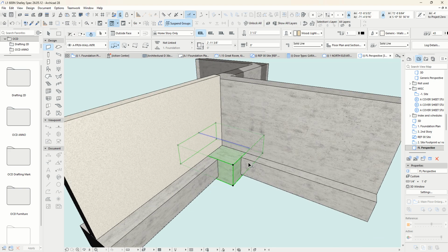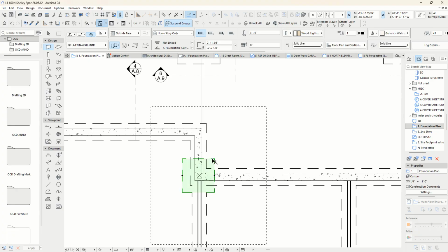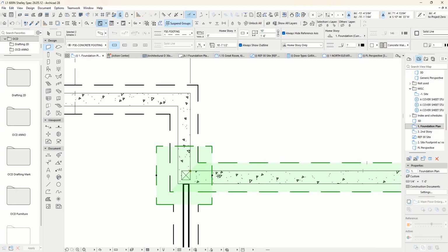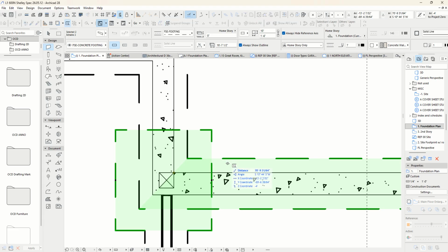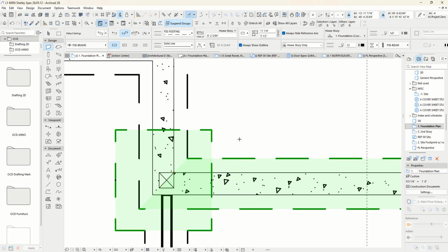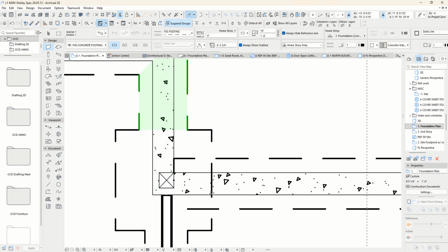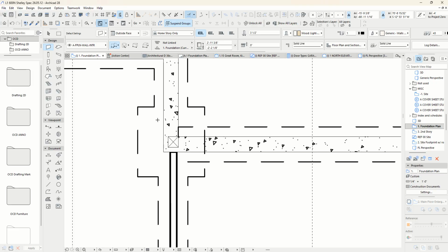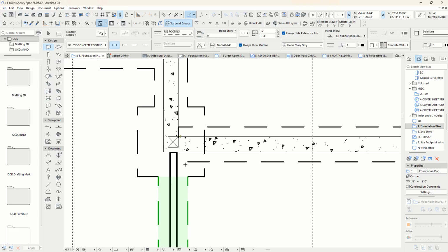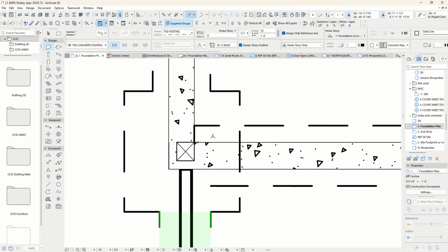Back to the footings. So these are beam tools. You can see the reference line there and the reference line there. And if I look at them in plan, I notice that my reference line for this one's down here. My reference line for this one's here. And so if I want those to merge, I have to move this reference to here. Now in the perpendicular direction, with this one merging onto this, all I have to do is extend this footing to the origin point there and see how it smooths right up. And that's the same thing this one has done, as I've gone to the reference line.